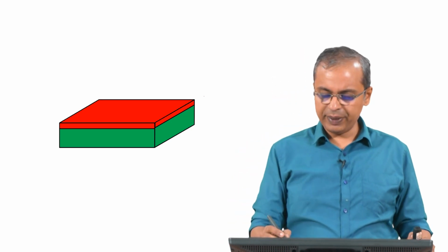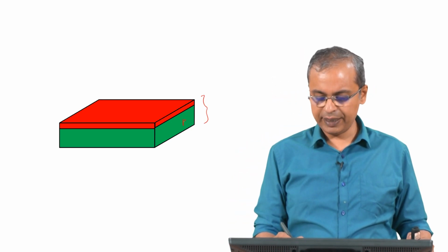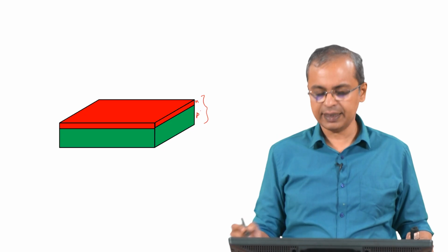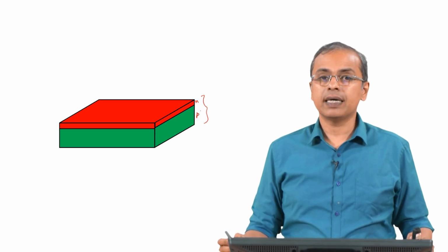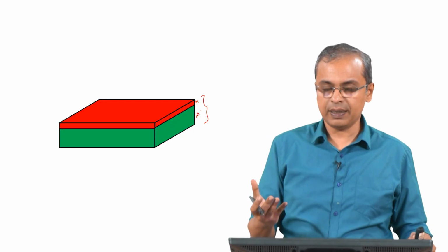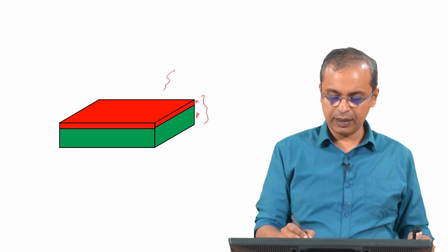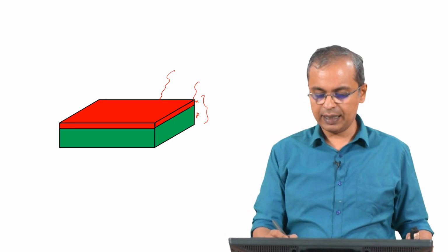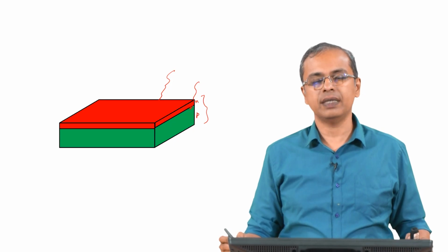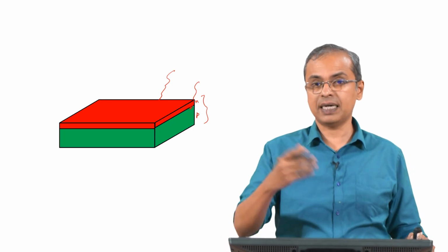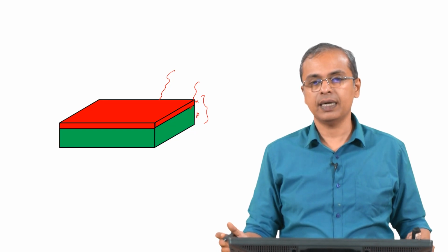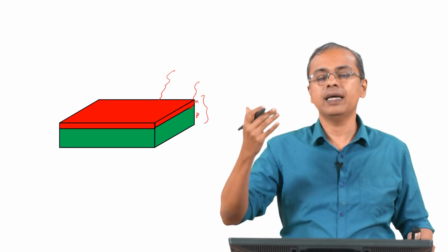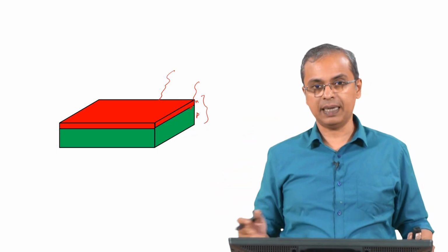So, the starting point is the p-n junction. So, I will say this is the p material and that is the n material that is there. So, this is p and that is n. So, that is what we have. Clearly you have solar radiation that is coming in and it penetrates this material, arrives at the junction, and then at the junction you have the charges getting distributed, and then you have the build up of charges, you have electrons getting built up in the n side, holes being built up in the p side, and then you can tap it to the external circuit.